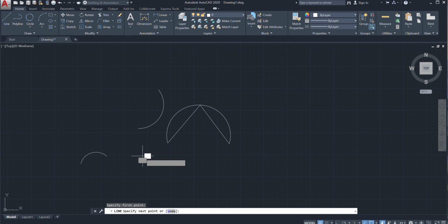First I'll show how to draw the door. As I told, ortho mode: why do we use ortho mode? To set the cursor to 90 degrees. To set the cursor, I'll press F8. Once you press F8, ortho mode automatically turns on. The door size standard, I'll take as 3 feet. Enter. Repeat command with spacebar. Specify the same, select the point, then 3 feet, enter, enter.